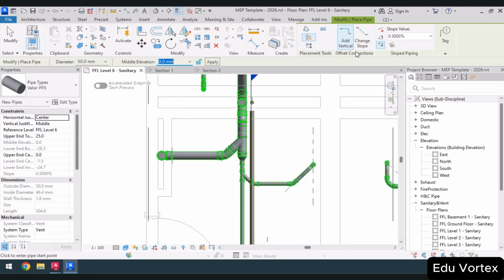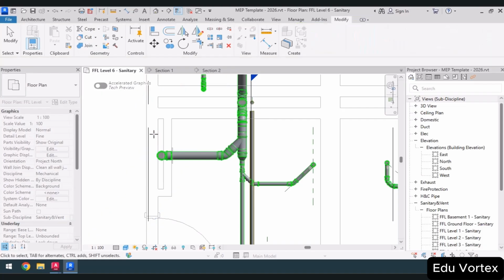The slope of my vent is positive when I move away from the fixture, which is the opposite of the wastewater slope. Here I can click at a 45-degree angle. However, it doesn't need to be at 45 degrees since this is a 90-degree elbow that will rotate. I must ensure that I come close enough without interfering with the flush tank.